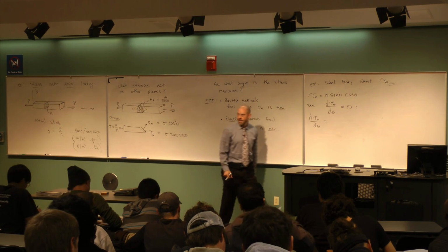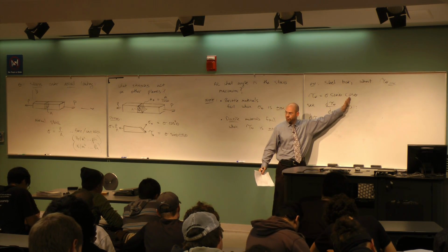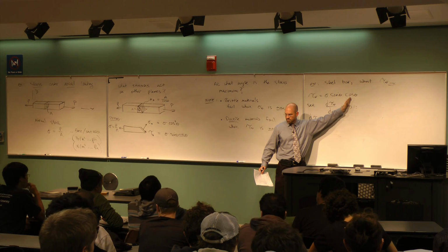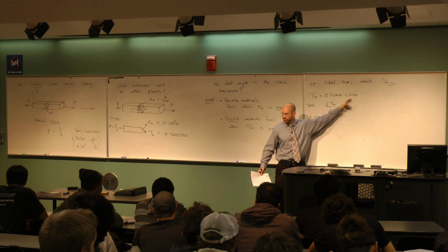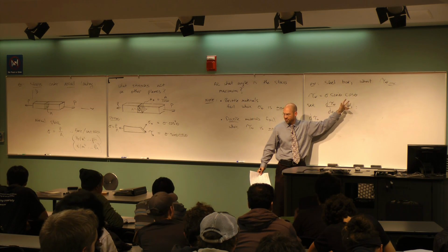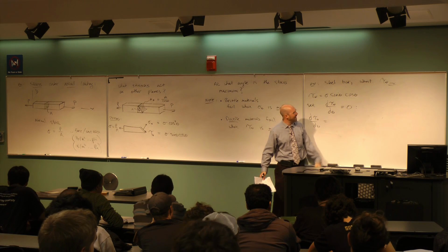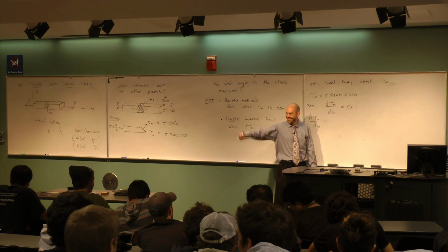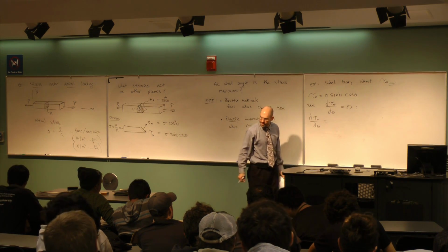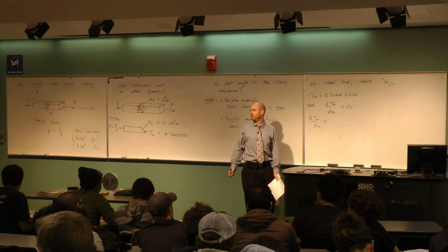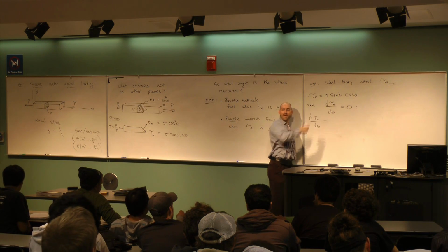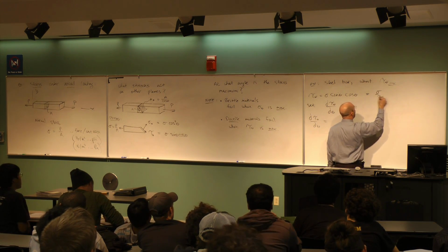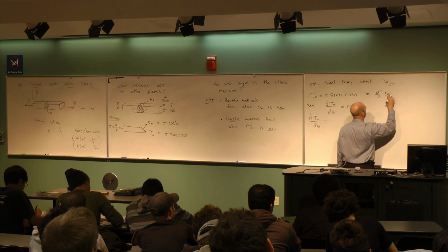Well, I got some choices here. This is a sine times a cosine, right? So to take that derivative, I could use a product rule. First derivative of second, second derivative of first. I'm going to get more sines and cosines. This is going to get easier or harder? Maybe harder. Can I do some trig on this first to make my life easier? It's a double angle. This is like a sine of 2 theta, right? But if it was a sine of 2 theta, there'd be a 2 here, yes? Sine 2 theta is 2 times the sine theta cosine theta. So if there's no 2 here, then I need to do what? Sure, this is sigma over 2 times the sine of 2 theta, right?